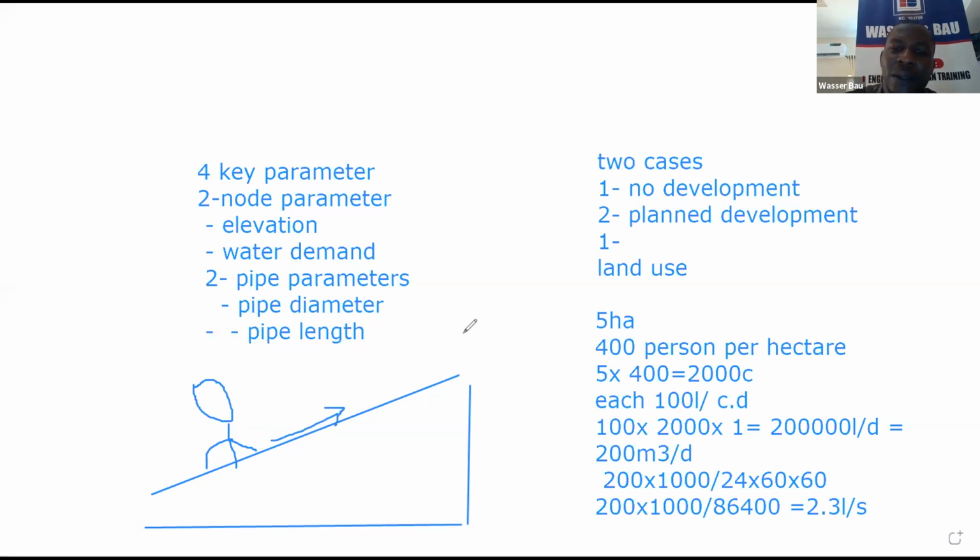So if I'm walking down here, and here is 0.310. Of course, here will be 0.290. And this distance is 200 meters. So my slope is this angle. And then by the time I walk this distance, I have moved by a height of, say, 2 meters.